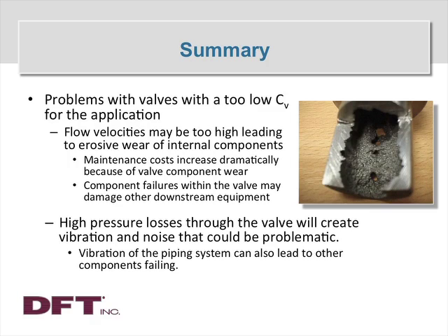Along with the high flow rate, you've got high pressure losses through the valve, and that's going to create vibration and noise that could be a problem all by itself. And so if you have noisy valves or a pipe that's vibrating, you might very well have a high flow condition that you need to look into. If you have what sounds like rocks going through the pipe, then you have cavitation going on. If you have small rocks, you've got a small problem. If you've got big rocks, you've got a big problem. But that sound of somebody dropping rocks on the pipe itself is a very solid indication that you've got fluid cavitation going on inside the valve.